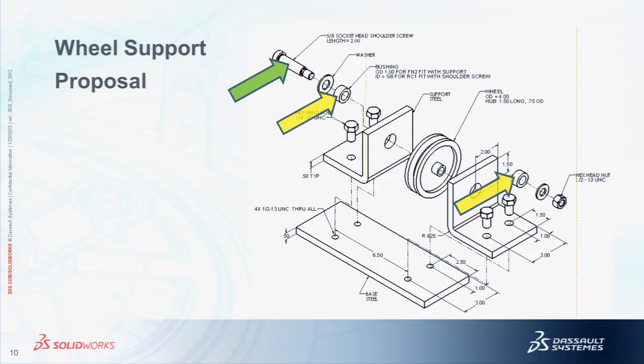Probably the other big thing with this is after everything is down, you notice that it's a line-on-line fit between the wheel and where the supports end up, meaning that it's probably going to bind up. So it's funny to see some of the proposed solutions. Well, I'm going to get pins. Everybody's got dowel pins. I'll get those babies lined up.